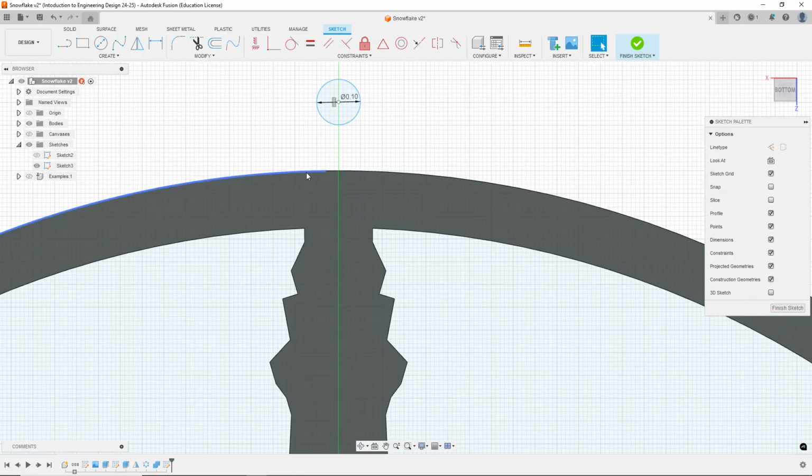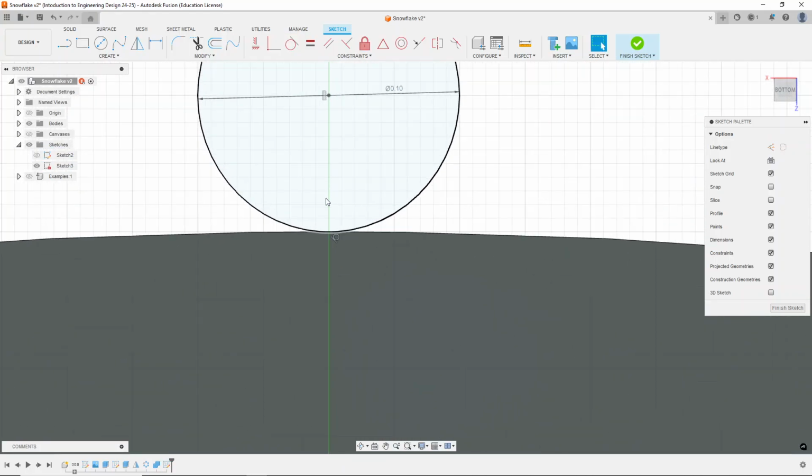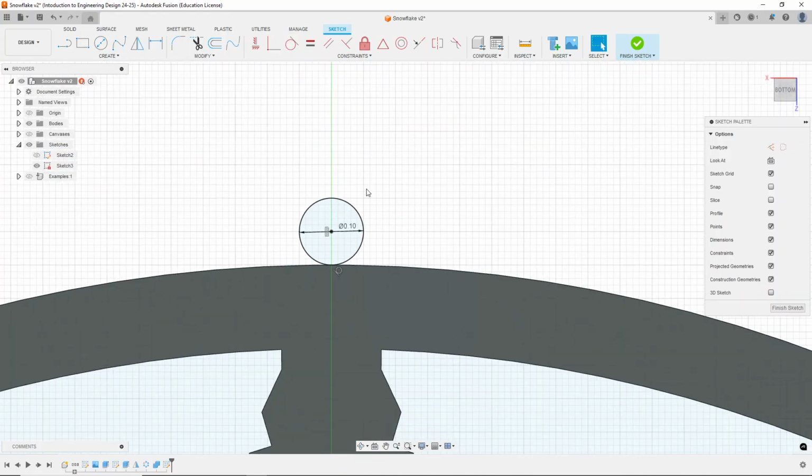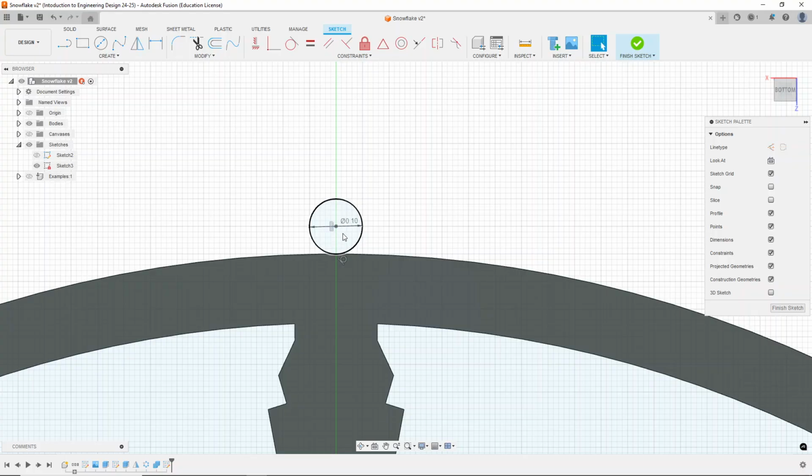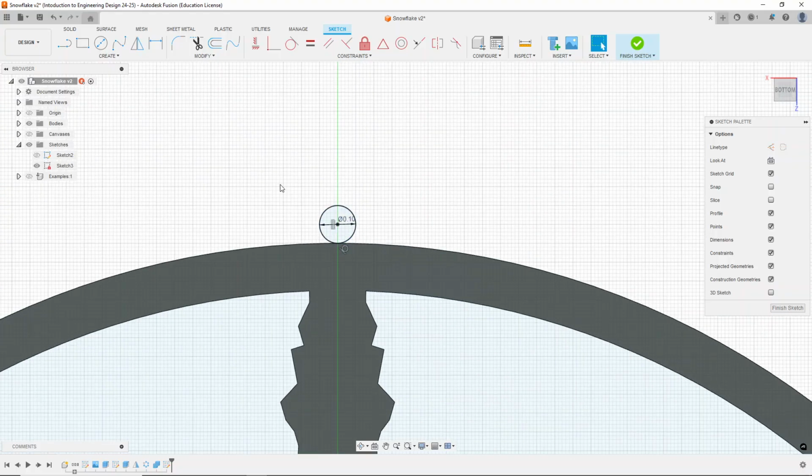And then I think I'm going to have mine be tangent with the top. So I'm just going to build the hole off of the top of this. So tangent, well, maybe I need to reverse that, no, sure, this line be tangent with that. So now I've brought my circle down, that is going to be my hole for the hanging piece of string. So here's that.